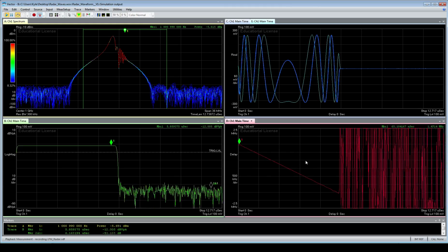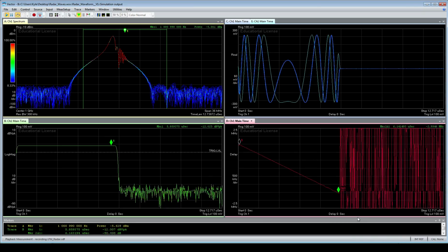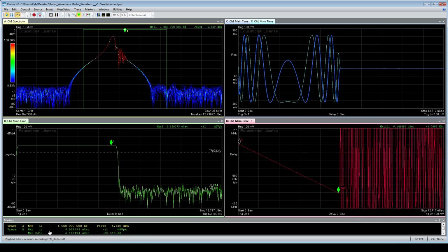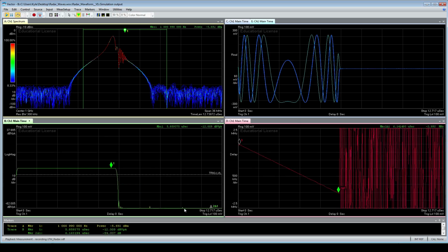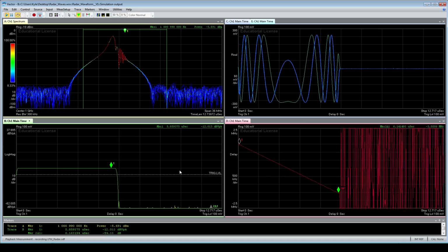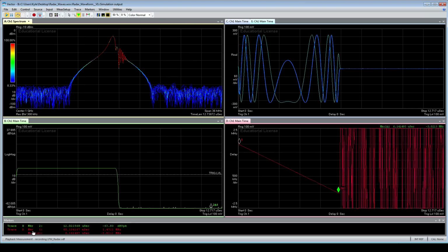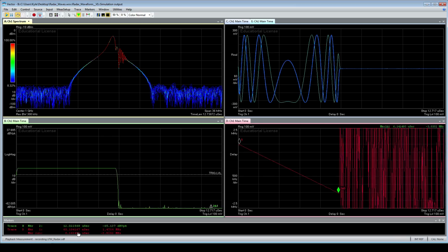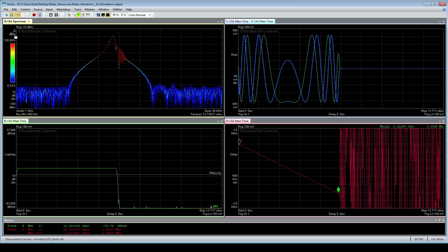If we wanted to, we could measure that with markers. Change our marker to a delta. And down here I'll actually clear these markers off. Yeah, we'll get rid of that guy as well. And we can see down here it traced D, marker 1 and marker 2, and marker 2, I'll pause it for a second, has swept over minus 2.994 megahertz.